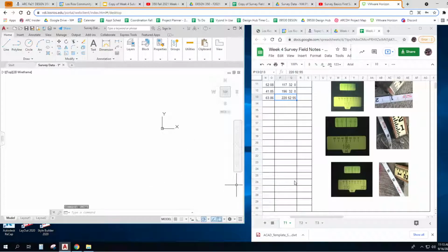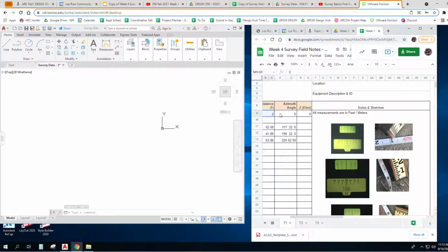Okay, now up here it says that my theodolite was set at 0, 0, 0 for the project. That's good. Every time you move the theodolite, you have to know where it is. Right now, I'm just telling our surveyors, pretend that's the 0, 0, 0 mark. We'll work out how to really peg where it is later on, but that's the more advanced stuff. So right now, we're just going to say where the theodolite was sitting is 0, 0, 0.